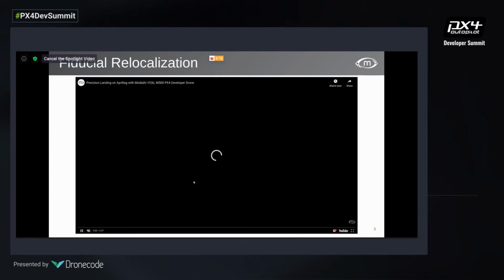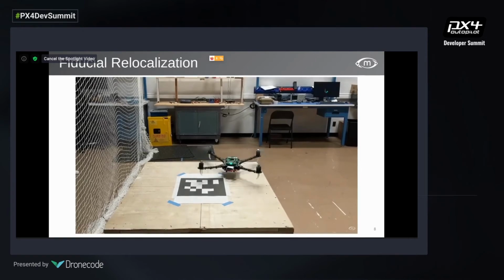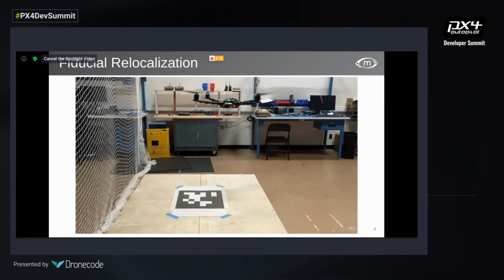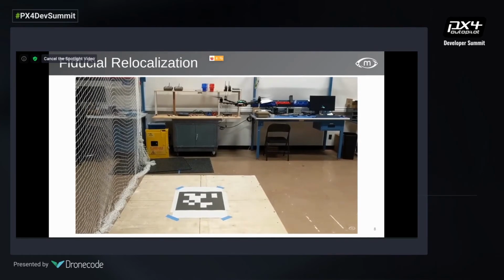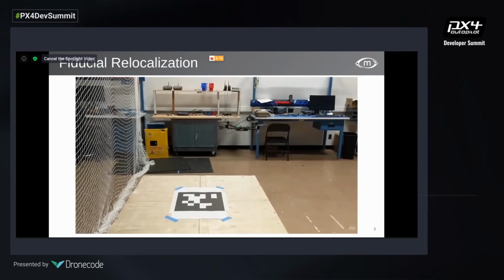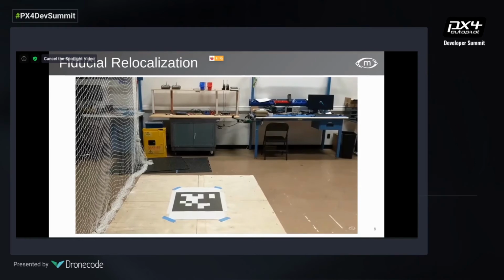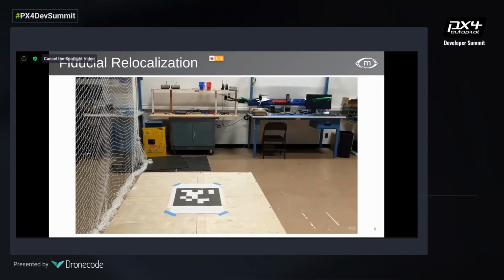Now, once all of those are in place, you can start doing something a bit more advanced. So here the drone has started with the VIO frame purposefully offset and crooked from its landing pad. And I have a small Mavros-based node running, which has just told the drone to go forward and back a couple of meters along the line of whatever its x-axis thinks it is, which in this case is off crooked.